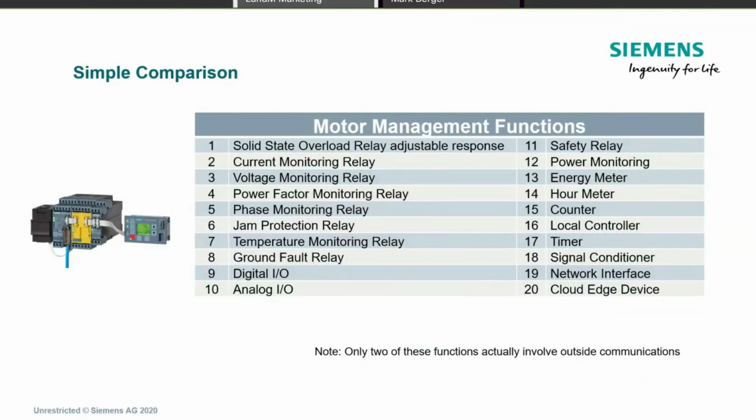You know, I've been in the electrical business for a few years. Back in the day, there was a Westinghouse reversing starter, and they had an add-on to it called a jam module. And this is an experience that I've had out in Wyoming at a facility that had some hammer mills. What they were doing was crushing some material, and every once in a while, this material would jam up the hammer mill. And instead of tripping the motor, they just wanted it to reverse. So what they used was a jam protection. And this is an old Westinghouse contactor.